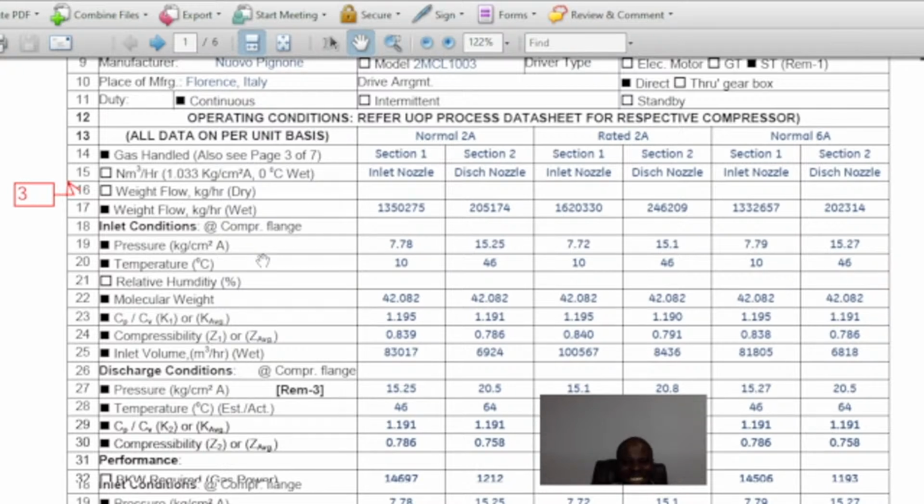So they are indicated by whom? By the process department. But they can be modified anyway by the manufacturer due to a different gas state equation used. But I need to state this: for compressor performance guarantees, manufacturer data should govern. So you must have this information.